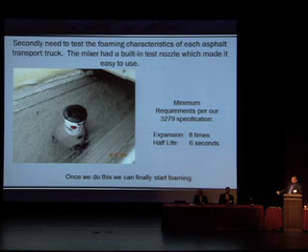Once you check your foaming rate, then you can go ahead and start your foaming process. And the way it works, you have a train, essentially. Your asphalt truck can be either in the back or in the front, and it is pushed along by your mixer. Your water truck can either be in line or behind, and they're both injecting the asphalt and the water into the mixing drum. I've got a little video that shows the process.